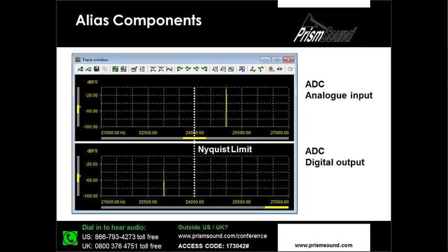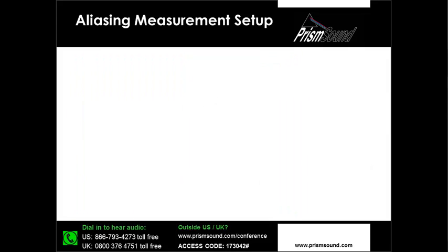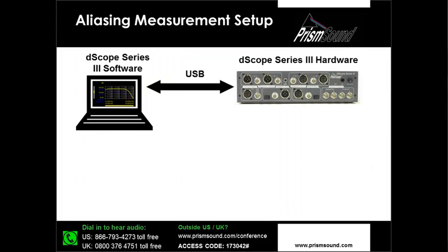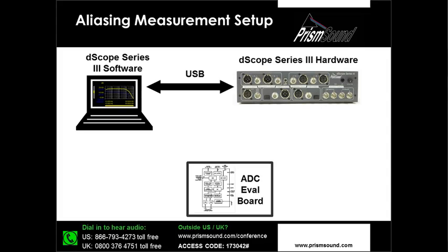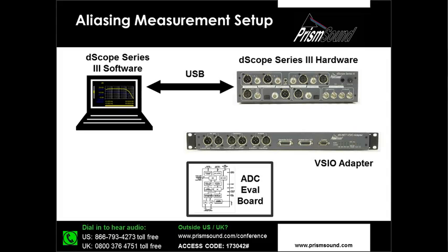It folds back down below the Nyquist limit, and the frequency of the tone gets lower as the input frequency gets higher. And you can see in this example the effect of the anti-aliasing filter here, that the tone amplitude is reducing as the tone wraps back down towards the audible band, ending at 20 kilohertz. So the anti-alias filter is something that we might want to characterize as part of our evaluation of the converter device.